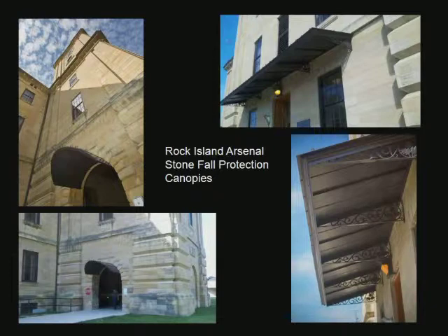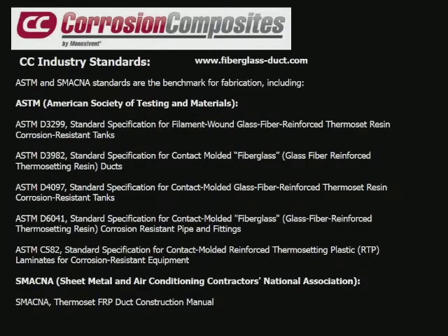That interior layer is a corrosion barrier, and we can fill that with a graphite powder. We can use a carbon veil, which is conductive, and that can be grounded, and that is a typical application for grounding duct systems.